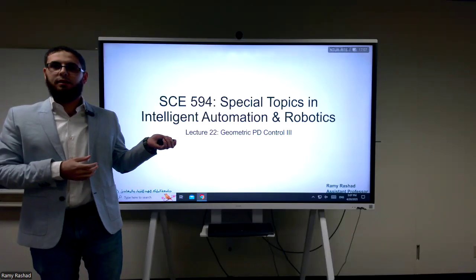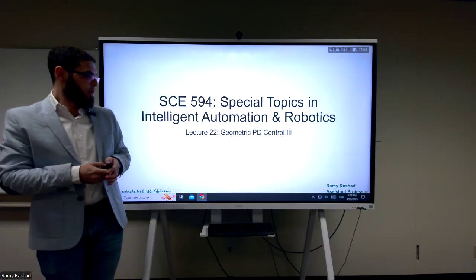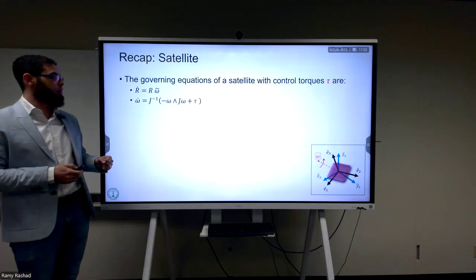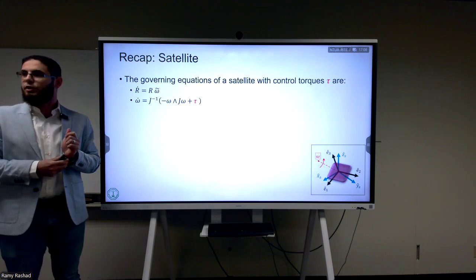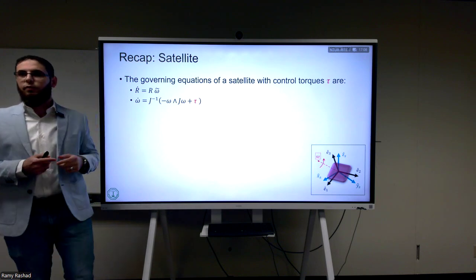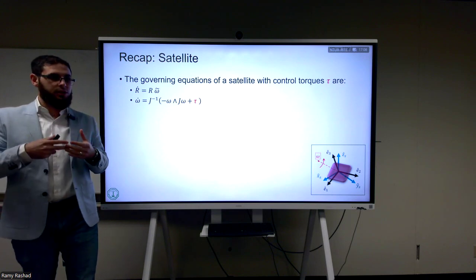Today is the last lecture in this series talking about geometric PD control. Let me start as usual with a recap of what we discussed in the past two lectures. We're considering now the geometric proportional derivative control on SO3, just as an example for a manifold, and how we can do geometric control on such a manifold.